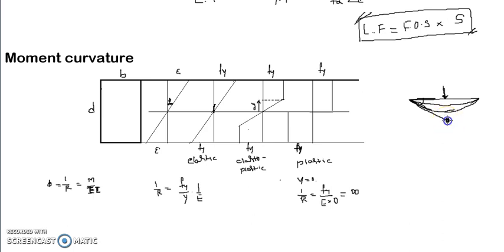The hinge has the same meaning as a normal hinge, but this becomes a plastic hinge. So it will go for infinite rotation. You cannot imagine infinite rotation, but here we talk about a huge curvature, that's what we mean by a plastic hinge.